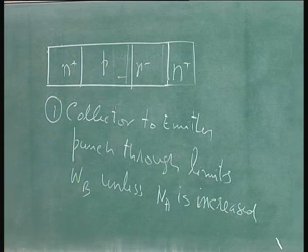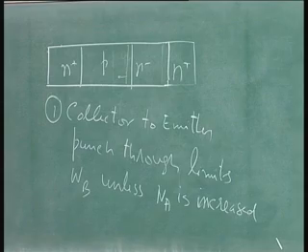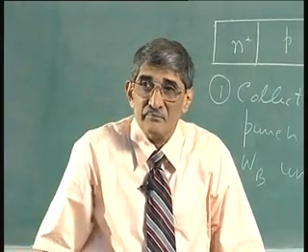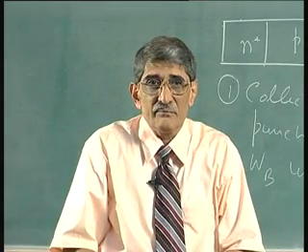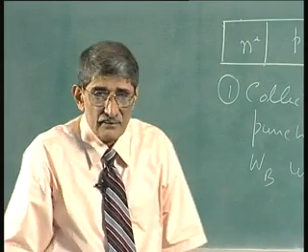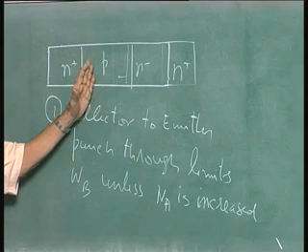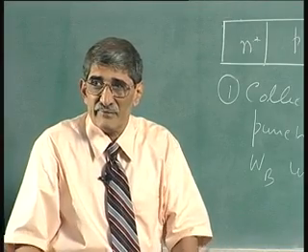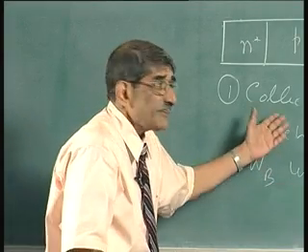You may like to go to 10 to the 17, 10 to the power 18, that level, when you go to that level of 0.1 micron, but then you will have a lot of problems associated with that. Let us see. So, this is following the usual scaling laws. Whenever you scale down, the doping must be increased, in MOSFET everywhere. What other parameters are there?